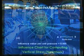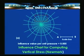If we want a different depth, we need to convert the dimensions of the loaded area correspondingly to a different scale. So the depth decides the scale, and we can determine the influence factor by just counting the number of elements that come within the given area.